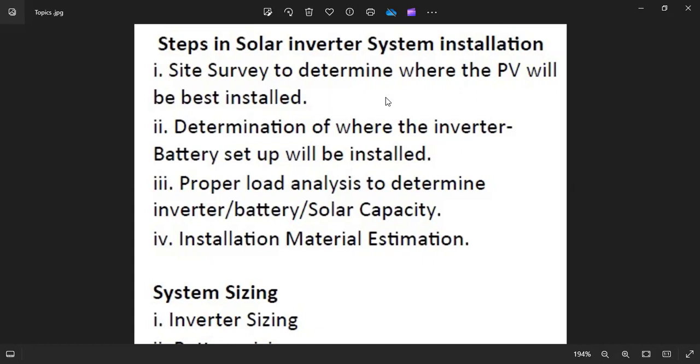So now, how do you install it, or what are the possible things you need to look at when installing it, as per location, as per where you want to install it? If you look at lithium-ion batteries, because of the high energy charge density, they are actually explosive in nature, and if they fail, they can emit a lot of dangerous gases.